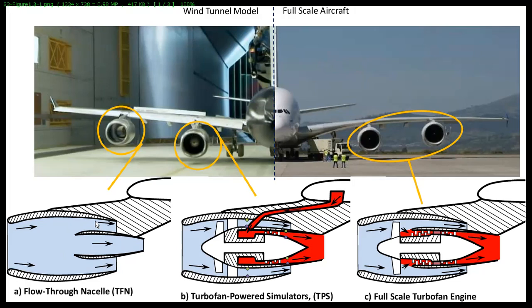There was a change in the engine. In the new model of Boeing, they put a very big engine, the LEAP, with a bigger and wider nacelle. And this bigger and wider engine nacelle changed the pitching moment of the aircraft, and the aircraft became unstable at high angle of attack.